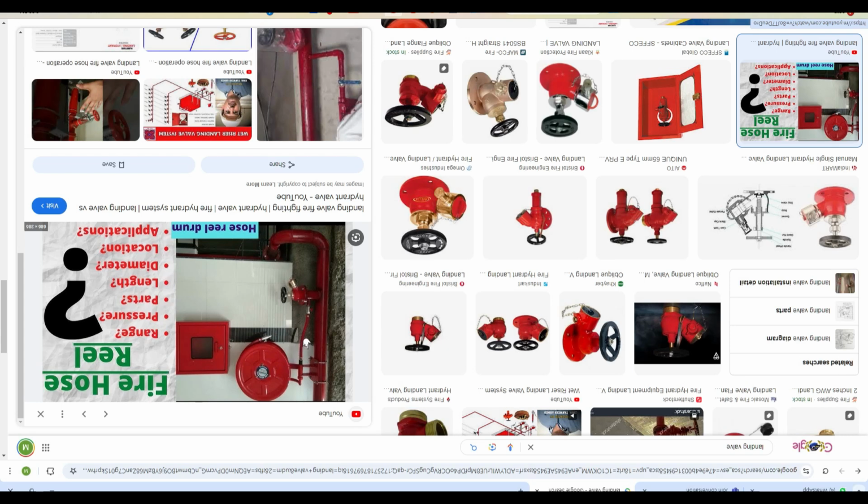Okay, but for the building type you are going to work on, up to mid-rise, unless it is a very small villa or a G+1 or 2 building, you will always get both in combination. But if only one comes alone, it does not mean that the design is wrong. That can also happen. So in that case, don't say your building is small, and if only the wet riser is coming, then don't think that the design is wrong.